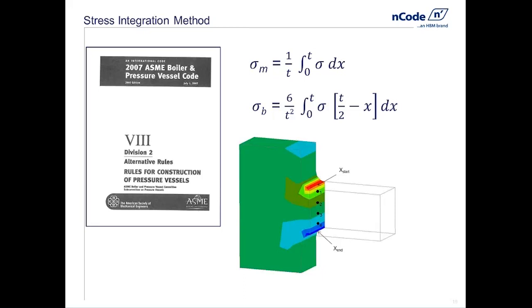And the stresses that we're calculating here are basically a 2D stress tensor that would be in the plane perpendicular to the normal that we're going through. So we would be calculating, in essence, a local sigma x, sigma y, tau xy at each one of those locations. And again, those planes would be a plane perpendicular to the stress linearization line.